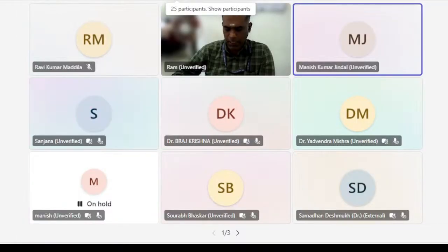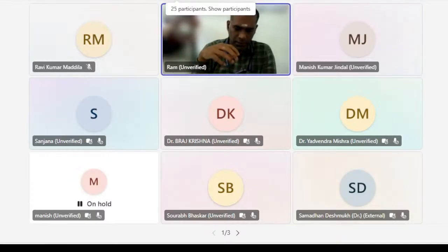See, residual stress is nothing but the stress induced by the process whose value is lower than the yield strength. Only then is it called residual stress. People typically use X-ray diffraction as a non-destructive tool to characterize the residual stress. You can go for the hole drilling method using strain gauges, but these are destructive methods, so people don't use them. Either you fix an interferometer or a strain gauge, you can measure the residual stress, but it is not advisable because it is destructive.